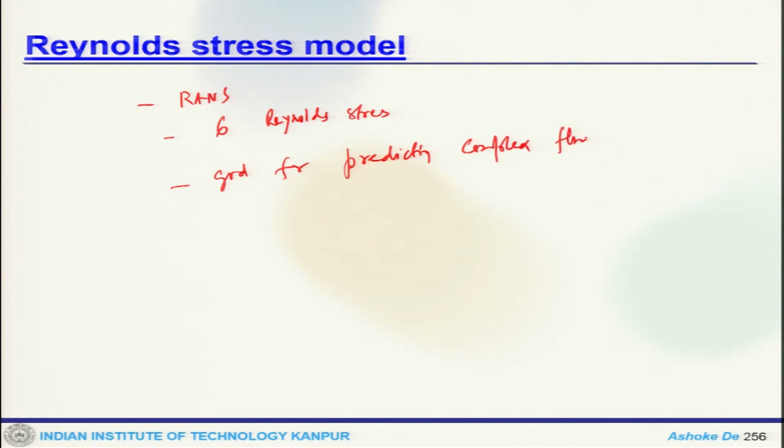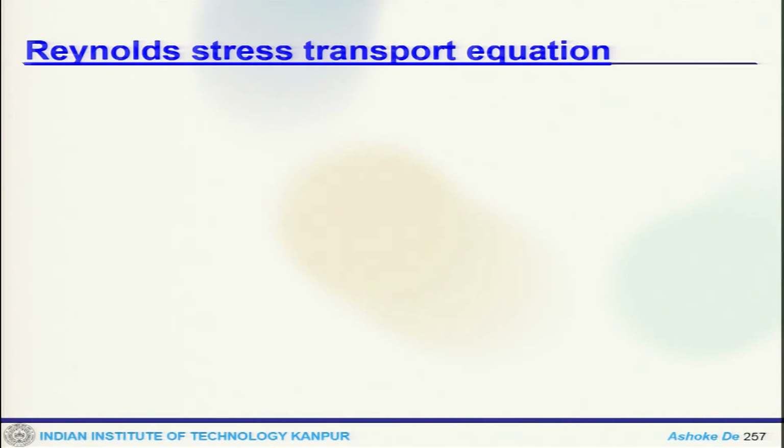So, it accounts for the streamline curvature, swirl, rotation, high strain rate. So, this can be used in combustor calculation, cyclone flows, rotating flow passages, secondary flows, flows within separation. So, this is quite a bit of improvement, and the exact equation looks like Pij plus Dij